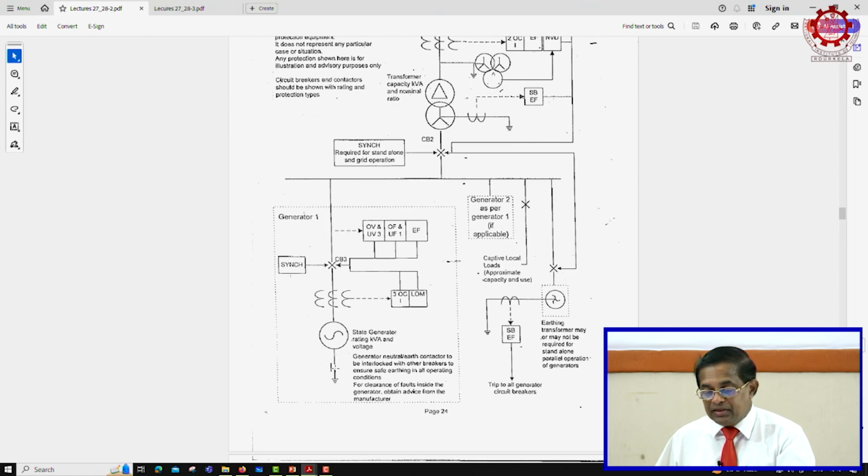Now, consider the situation where this circuit breaker trips for some reason on the network side. Our generator may then be running with the loads available in the power plant. If the water is very low, it has a very small generation, it will balance the load requirements of your power plant and it can run. Now, you have a system here without an earth.